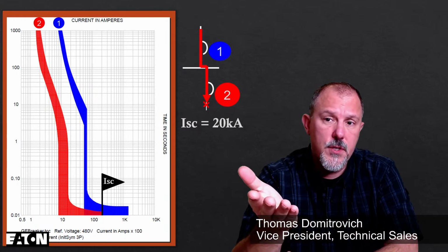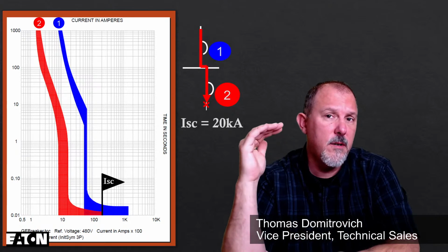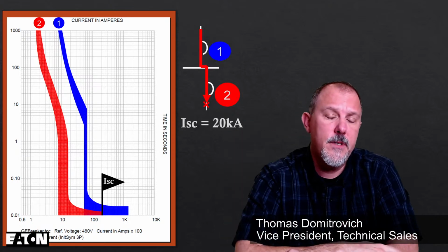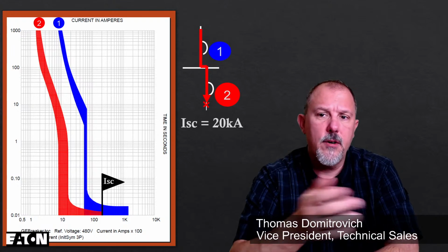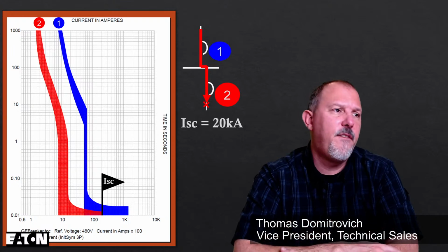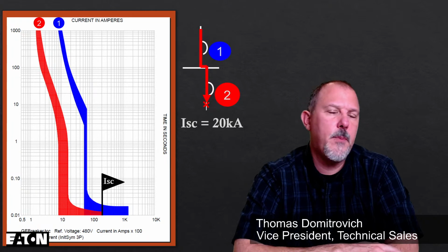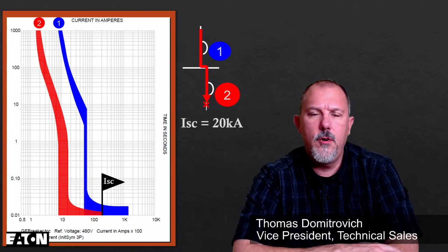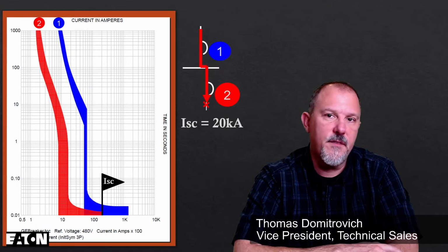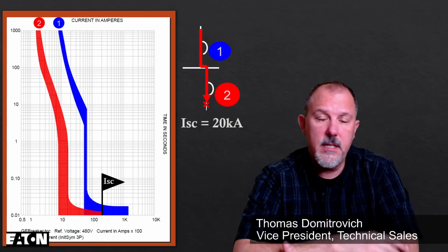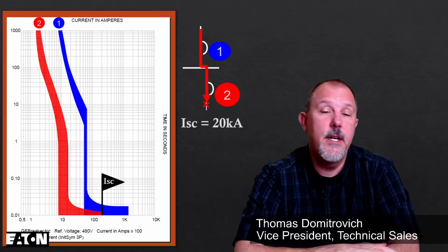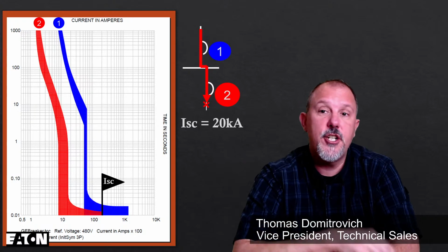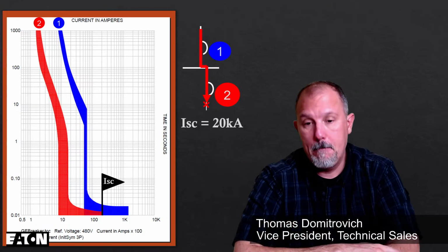And these curves are applicable around a temperature range. So I don't see loading effect. I mean, if I have a 40 amp breaker loaded with 5 amps as opposed to a 40 amp breaker loaded up with 20 amps, it's not going to make a difference. Not in these TCC curves. I don't care if you had that 20 amps running for 3 days and then decided to ramp it up. You're not changing the characteristics of that breaker.